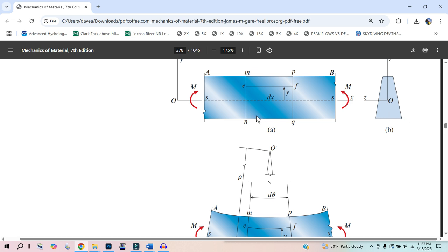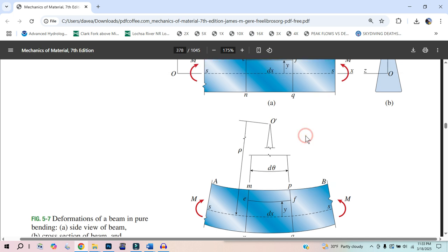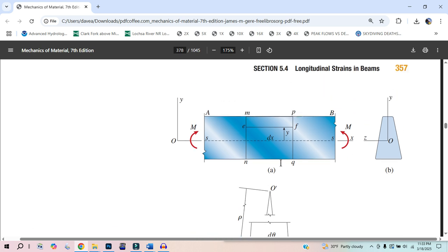If I make a simpler problem, let's slice this beam right through here, and then just take N and Q on its own, and then just pull on it, and then get it to this length. That problem is a simpler problem. You know what I mean? It has this area, and I would know the force required to do that. So now we've related it.